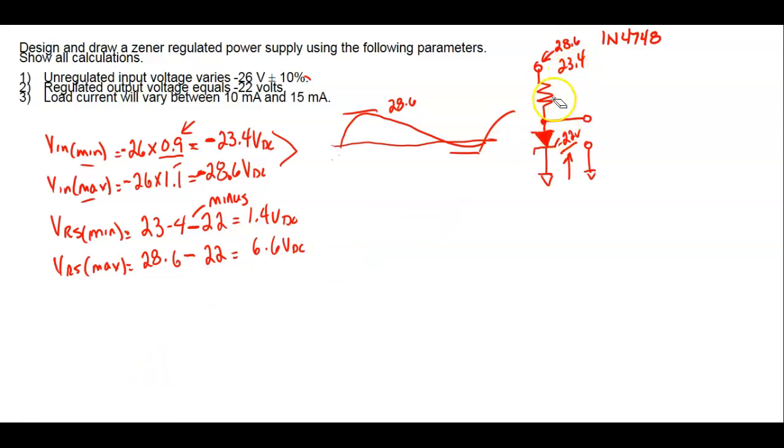So what we're trying to do is figure out what resistor I want to use. We know we're always going to try to make the zener current go away from the knee. This is why, to understand these formulas without memorizing them, we always want the zener current to move in this direction right here. We want it to go up. We don't want it to go down.